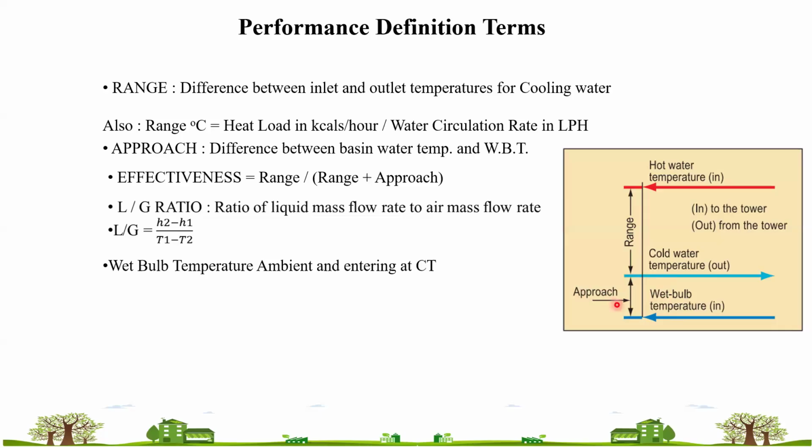Nowadays people take a cooling tower with lower approaches, like 2.8 degrees Celsius, which is a trend in cooling tower purchase. Previously it was 3.2 degrees Celsius. Nowadays people are reducing to the nearest temperature, so the performance of the cooling tower increases.